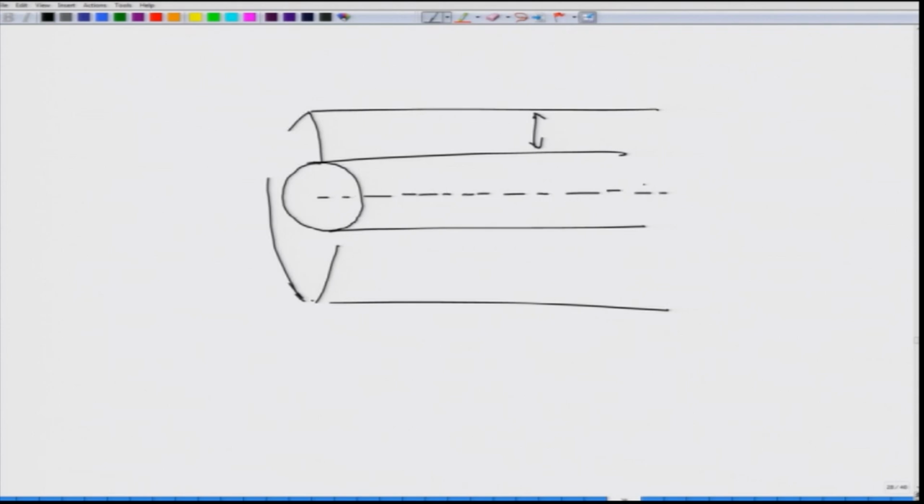I have exaggerated the core medium over here. What I have is that an incident light usually comes from outside the fiber. So, I wanted to indicate that one, hence I have indicated this optical fiber like this. This incident ray of light strikes the core cladding interface, the face of the optical fiber at an angle of theta 0. Outside medium, let us call the refractive index as n0, inside the core has a refractive index of n1 and the cladding has a refractive index of n2.